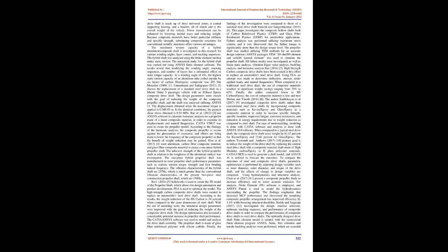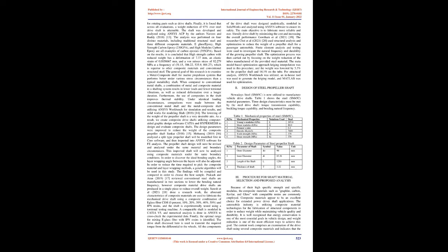Ravi, 2014. SolidWorks is used to create the 3D model of the propeller shaft, which allows for design automation and product development. FEA is used to optimize the model. The high-strength carbon composite drive shafts were created to replace an automobile steel drive shaft. According to the results, the weight reduction of the HS carbon is 24% when compared to the same dimensions of steel shaft. With the aid of modeling tools, the structural design parameters were improved with the goal of reducing the weight of the composite drive shaft.